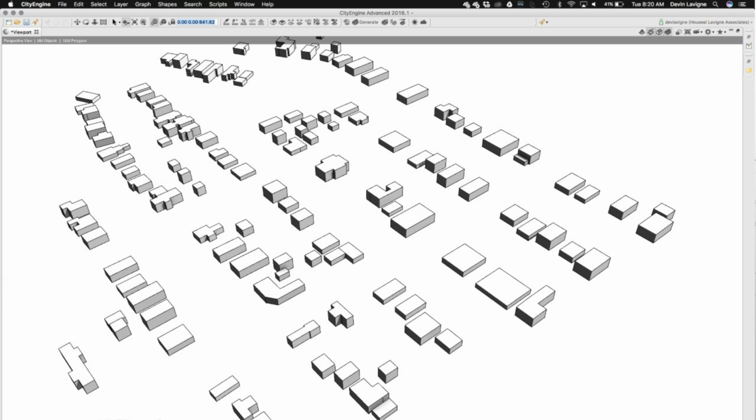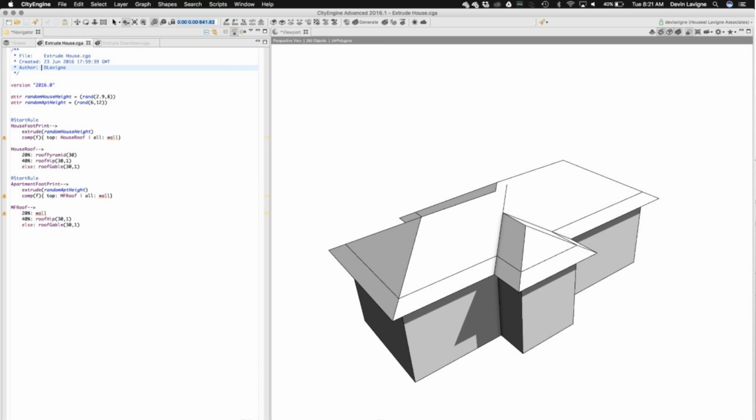Moving over, this is the same scene. This is a neighborhood adjacent to this site, and these are single-family homes, detached garages. Again, just that simple extrusion doesn't do a lot for the residential context. So a simple rule that we have here is called extrude house, and we can drag this onto shape files of any residential footprint.